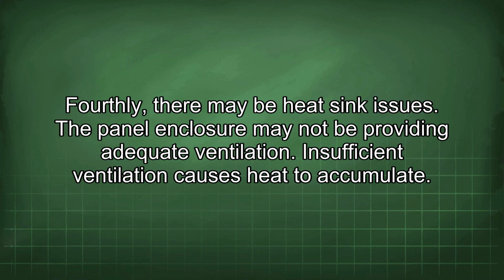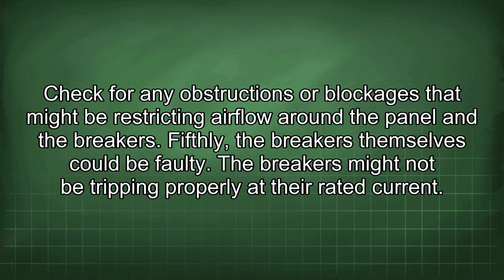Fourthly, there may be heatsink issues. The panel enclosure may not be providing adequate ventilation. Insufficient ventilation causes heat to accumulate. Check for any obstructions or blockages that might be restricting airflow around the panel and the breakers.